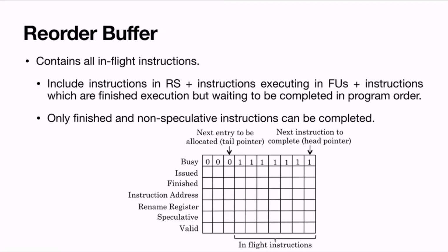The main idea here is that some of these instructions are already in the pipeline and have partially done their computations, so why can't we make use of that? That's the basic idea. We just complete the execution of those in-flight instructions, write them to the architectural register, and then go ahead with the interrupt service routine and come back to the normal program again.